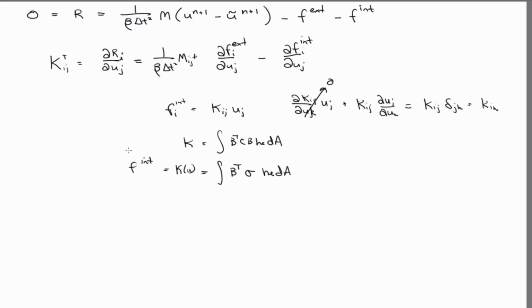But to maintain that quadratic convergence, remember in your F internal, in your stress, you have a return algorithm. You have some numerical procedure. You're off the yield surface, you've got to get yourself back on it, right? So you have some return algorithm to get yourself back on the yield surface. When you take that derivative, it has to be consistent with the return algorithm.